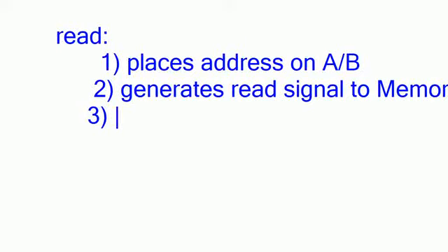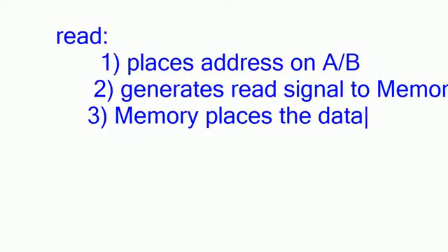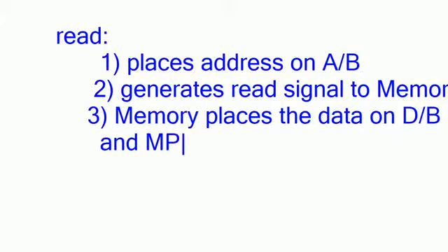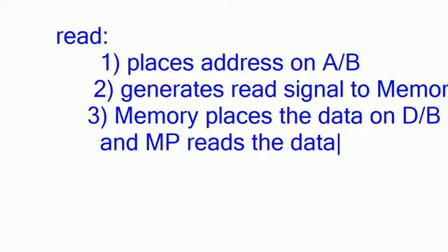Step 3: memory places the data on the data bus. I'm just using D/B as a shortcut. The microprocessor reads the data from the bus. So these are the three steps followed by the microprocessor to perform the read operation.